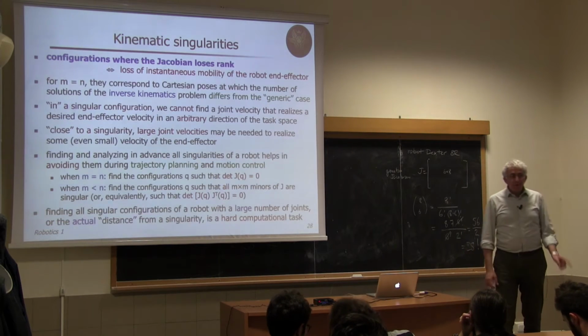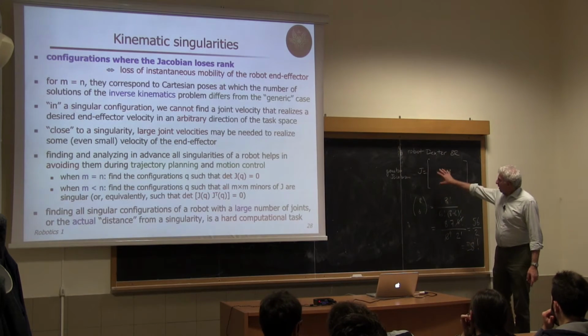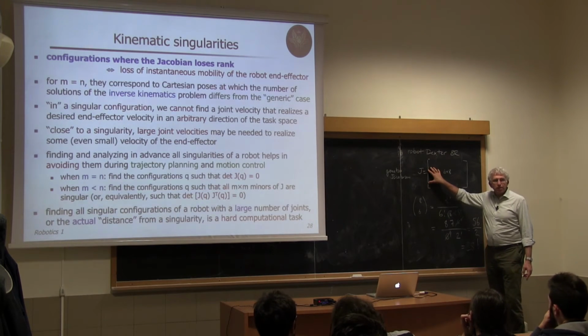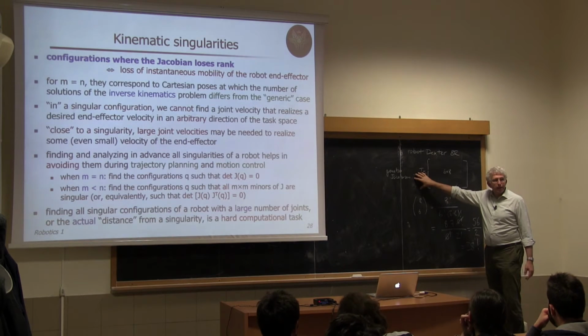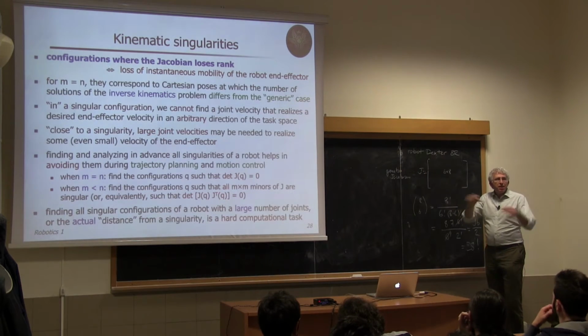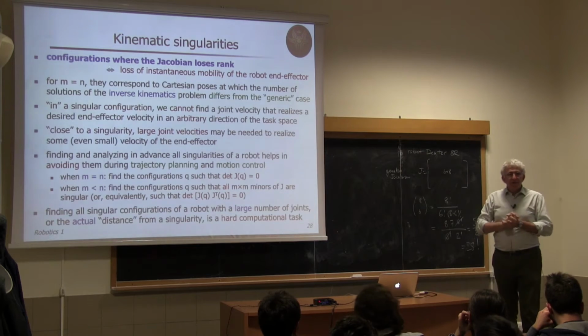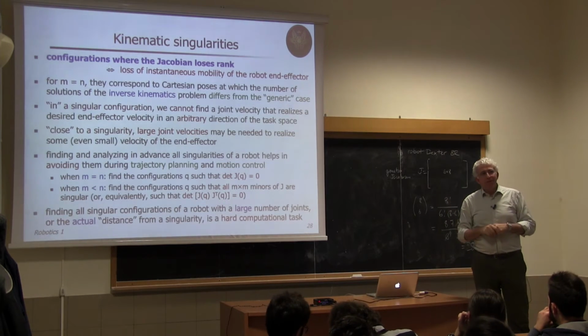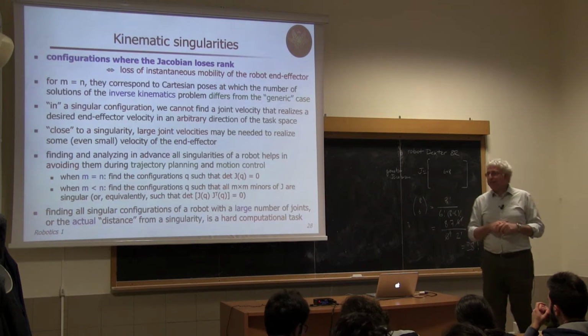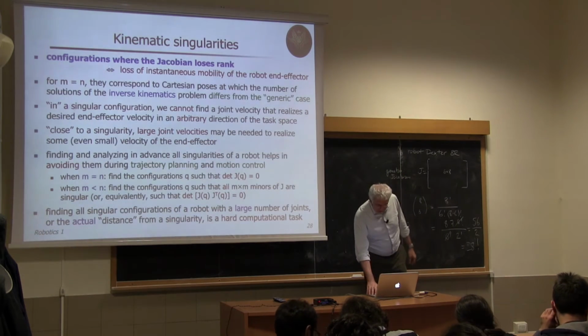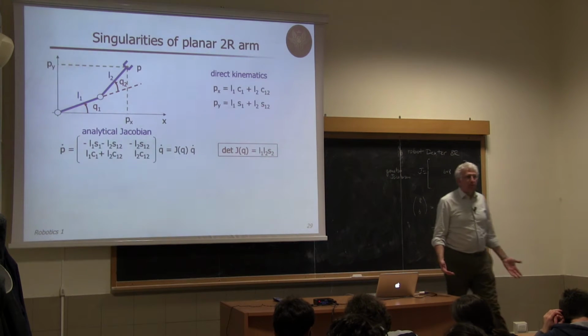This is why, if you want to do this, it's better to manipulate the Jacobian a bit. For instance, express it in some special reference frame where it is simpler, because if you rotate the Jacobian and then do the product Jacobian times Jacobian transpose, the rotation is gone, while what remains is much simpler. I'm just sketching the few slides that we skipped last time, to invite you to go back and look at what they say. Okay, so let's do some simple example of what we have said.